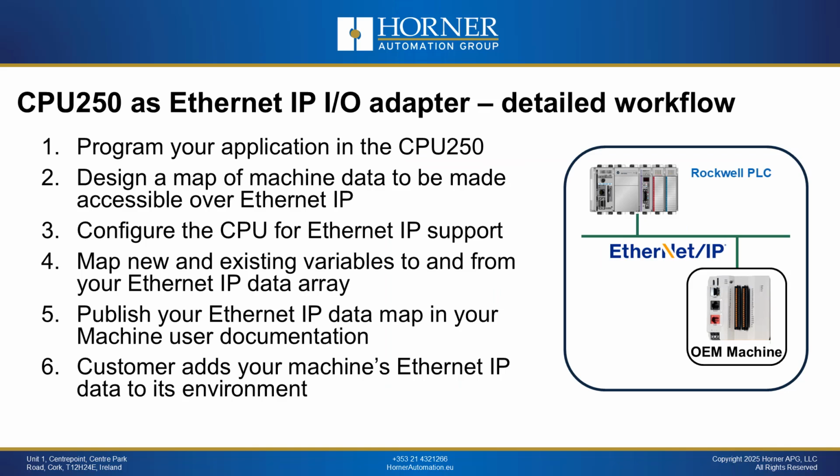A detailed workflow is when you are using the CPU250 to control your machine and you want to exchange data, or you want your customer to be able to exchange data from their Ethernet IP infrastructure to and from your machine. And here is what you need to do. First of all, you are going to program your application into the CPU250 like you normally would to control your machine.